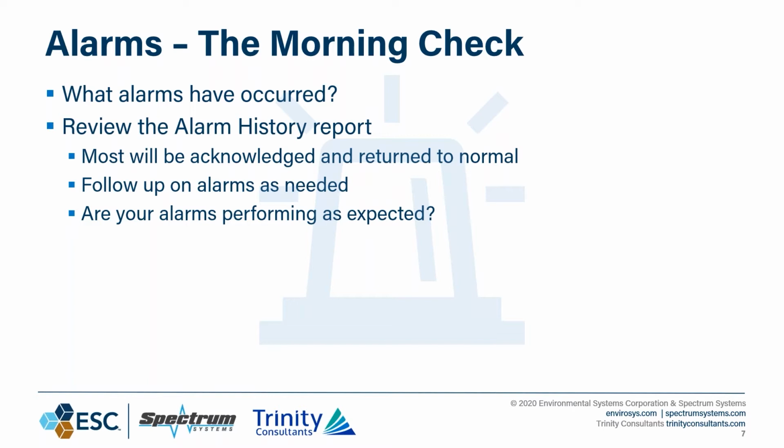If you have an alarm history report available with your handling system, you should probably be reviewing it. If everything is going according to plan, most of those alarms will be acknowledged and returned to normal. You should follow up on those alarms as needed. And really just as a gut check, once again, are your alarms performing as expected? Are they giving you the information that you want on a timely basis? Are they having the effect that they're supposed to?